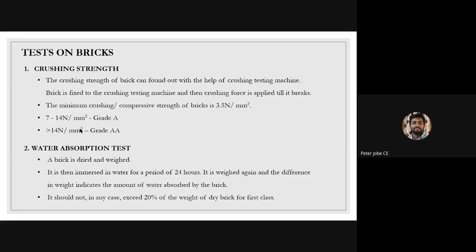We'll take a few samples of bricks and we will dry them. And then the next thing we will do is immerse them in water for 24 hours, and then again we will take them and weigh them.